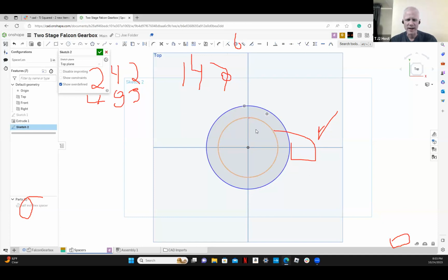So now we want to have a dimension where this one will slip over a 147 times 2. So flipping over, you need like 2 or 3 thousandths, something like that. So to be easy, I think I would just take like 0.15, multiply that by 2, and then, so that's 0.3.